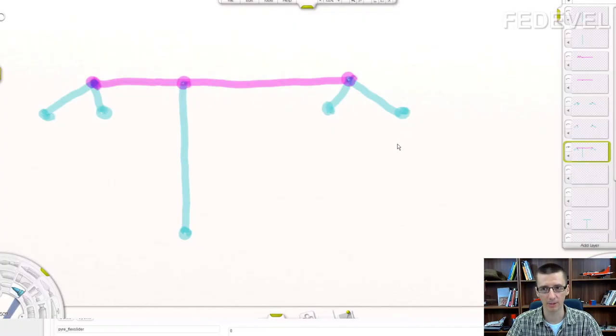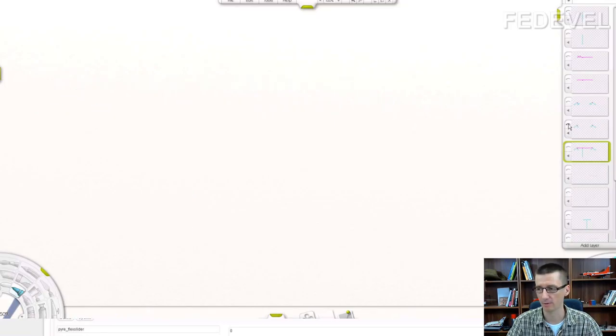When I do the length matching of this kind of signal, I do it in 3 steps. First step, I focus on these last segments here. I'll switch this off, switch this on. We know all these 4 segments, they need to have exactly same length. So I do something like this.